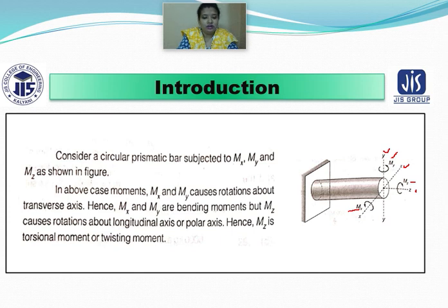And tau is the maximum shear stress at the outer surface, because as I have already told, due to this turning force or this torque, wherever we are applying this particular load or twisting force, that particular object is experiencing some shear stress also. That's why tau in this equation is represented by the maximum shear stress at your outer surface.